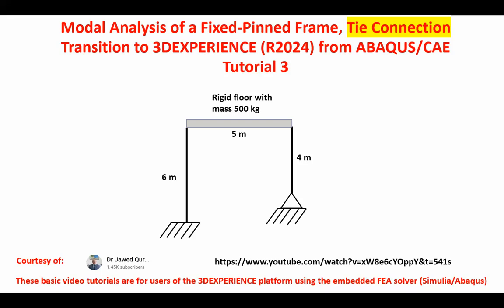So when it comes to meshing the vertical column, you get a certain node on the top, and when you mesh the horizontal beam, you get another node on the top. But because I asked for the 2 nodes to be merged using that particular checkbox, it essentially created this common single node at the junction between the beam and the column.